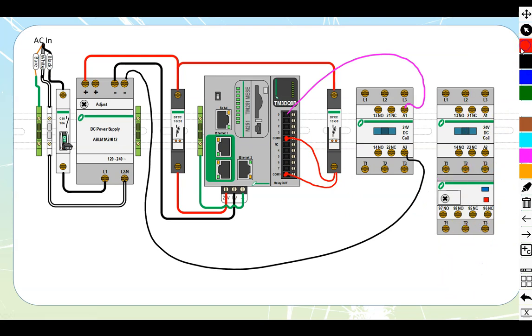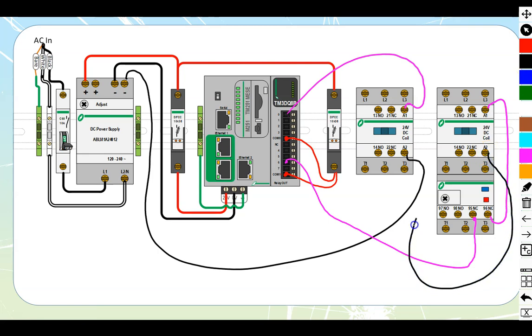So we will take our power out. So we'll take this one here. Let's pick it from number 6 over here. We're going to take that number 6 out. We are going to feed it in through a normally closed contact over there, then out of that normally closed contact up to my A1 like that. And now that we're at my A1, all we need to do is take my A2 all the way back. We'll tie it in underneath this screw over here, no more than 2 wires under a screw. And now we have a path all the way back from my DC.